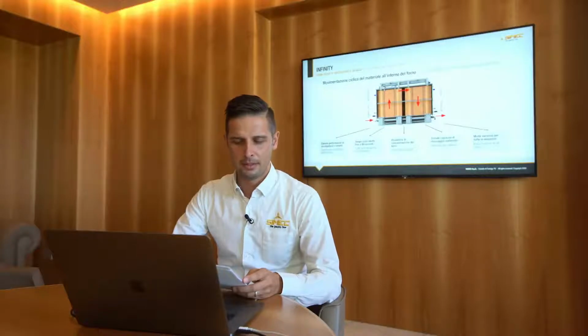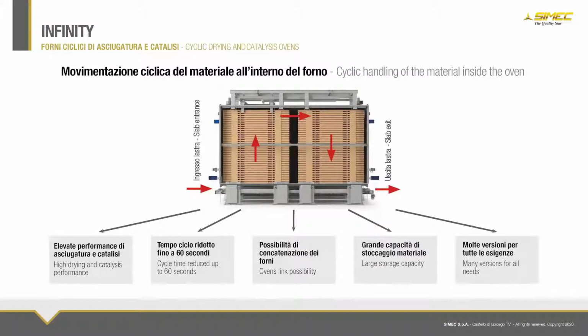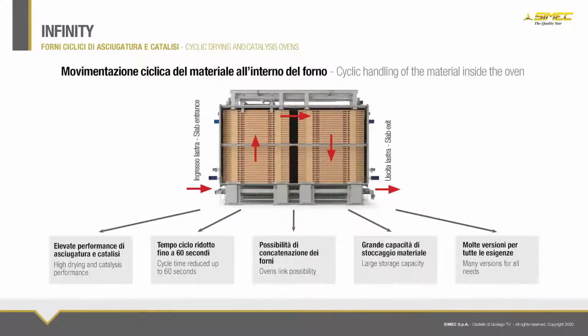The slab lifting system of the Infinity oven is hydraulic, guaranteeing the highest reliability and accuracy standards. The plant has a parallelism compensation system that ensures a planar lifting of the tray thanks to the use of linear bearings. Each hooking and lifting point of the tray is guided by a double ball bearing guide, guaranteeing a fluid movement. In this way, the movement of the material is extremely soft, with low excursions, since every slab moves each time by a stretch equal to the height of a level.